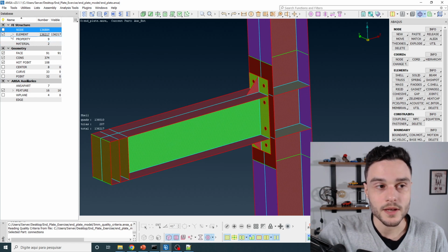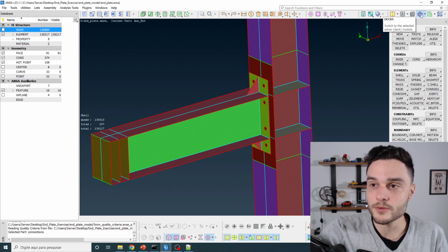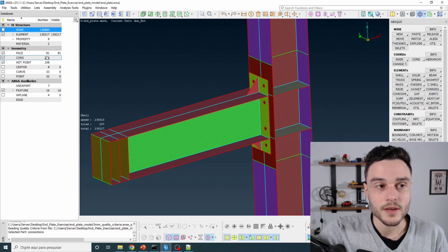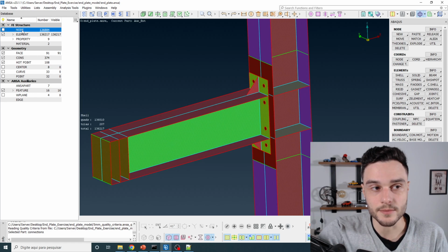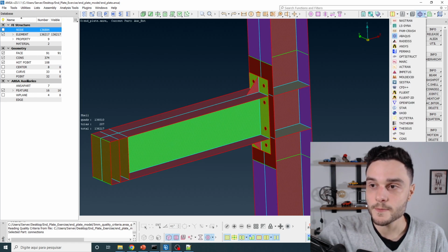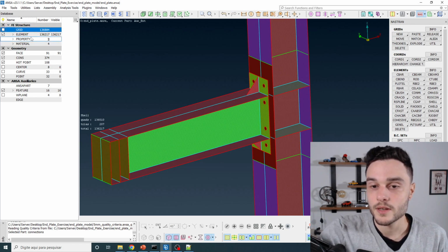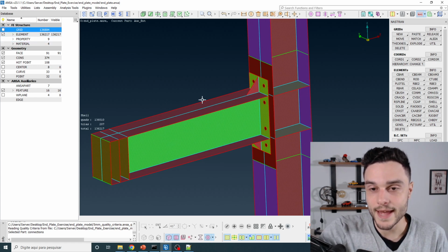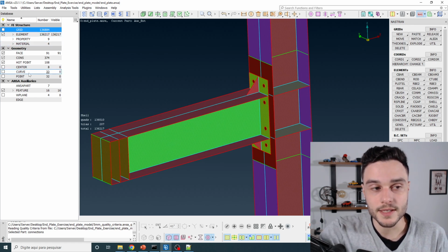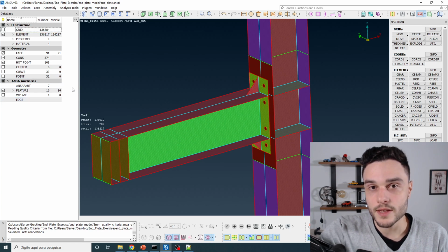For example, notice that when I have Abaqus selected here, which is the case, node is named as node, this first item. Now, if I choose here Nastran, then node is named as grid. Okay, it's just a different way to name some entities. So if in the previous videos, when I presented the database, you had something different, then that's the reason.